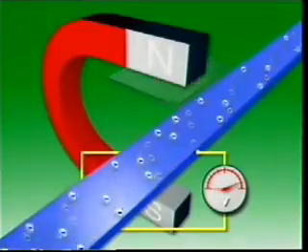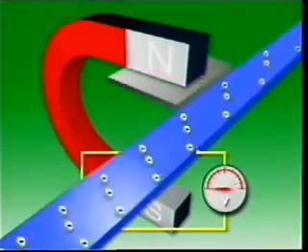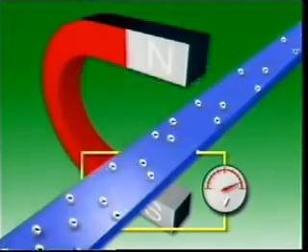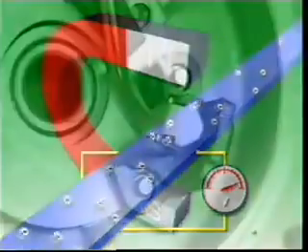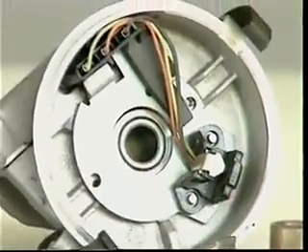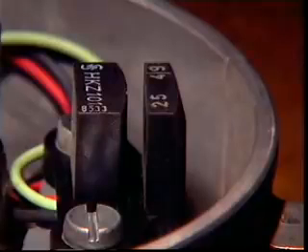This is called the Hall effect voltage, and if the magnetic field is alternately shielded and exposed, it can be used as a switching device. Hall devices are made of semiconductor material because it produces a better effect.